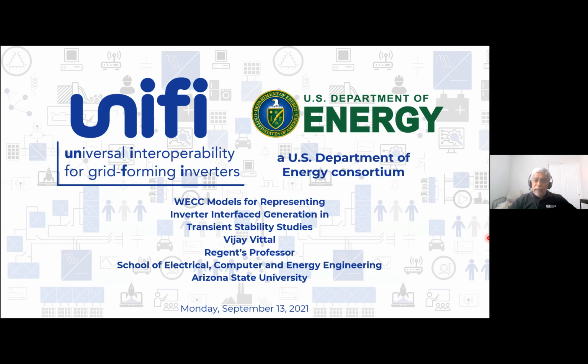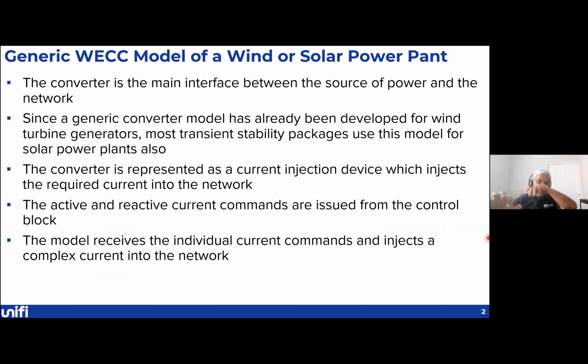And I assembled a set of slides here which highlight how generic models for DER resources, which are primarily inverter interface, have evolved over the years. And the basis for most of this work is to remember that our goal is to represent a large number of these DER resources in large scale positive sequence time domain simulation.